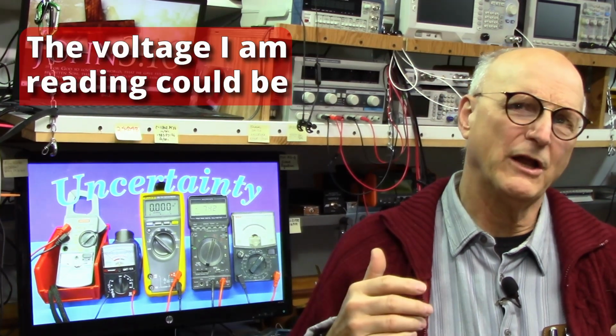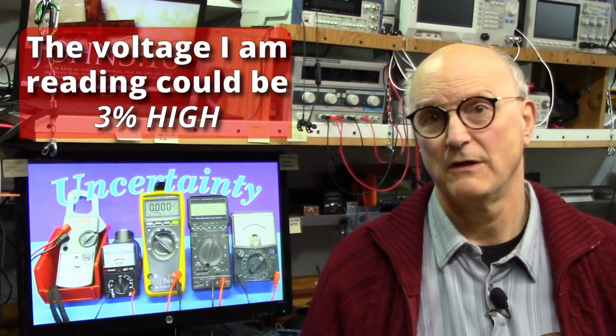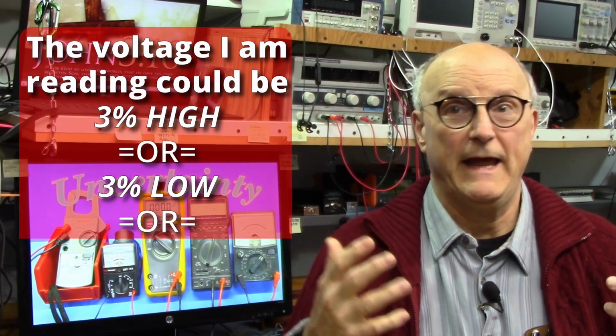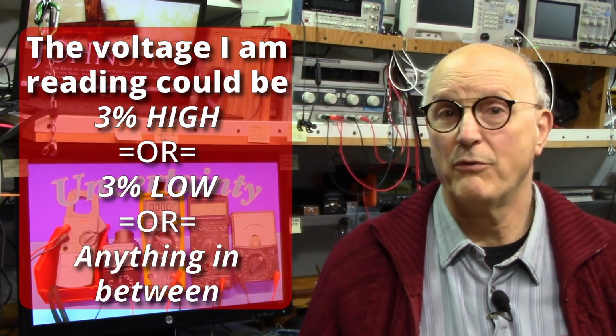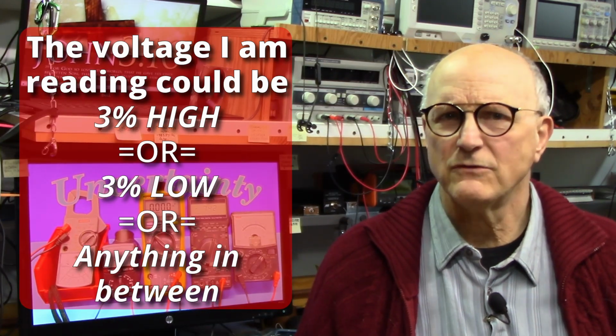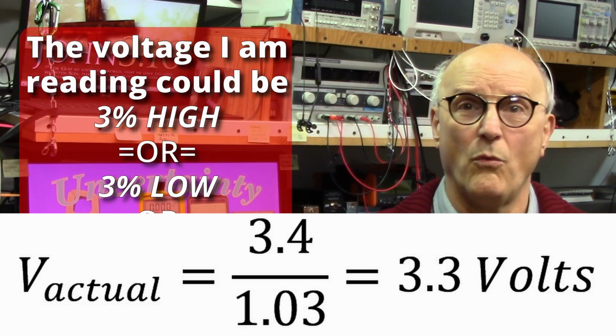Well, good luck on that one. What this means is that the voltage that I'm reading could be 3% high of the actual voltage, or 3% low of the actual voltage, or anything in between. So if I'm reading a voltage of 3.4 volts using this oscilloscope, then the actual voltage could be 3.4 divided by 1.03.